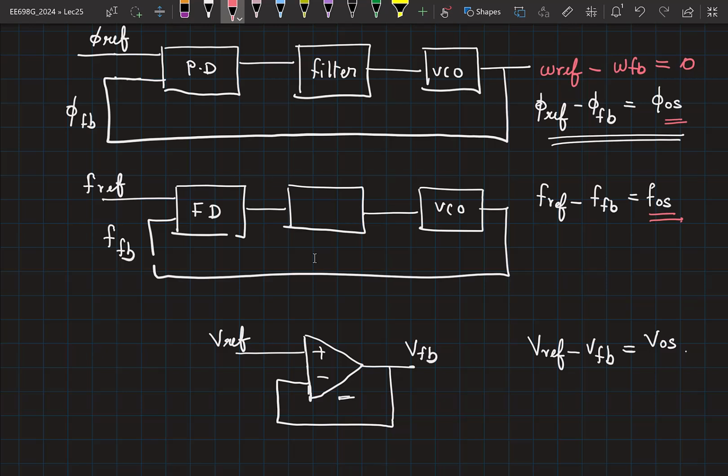For example, let's say you were designing a clock for a processor. You told the engineer that it is going to lock to some frequency. He did an STA analysis based on that, right? But then because you have locked with respect to the frequency, in practice you can have an offset. This offset will be constant for a given PVT condition. But if your process corner changes or temperature changes by a large amount, this offset will also vary. Which means you cannot exactly predict this value, you can predict the range of values. So it's possible that the STA analysis done earlier can fail because it was done for a particular time period. Now your time period has changed. Everybody understands STA? Timing analysis for setup and hold.